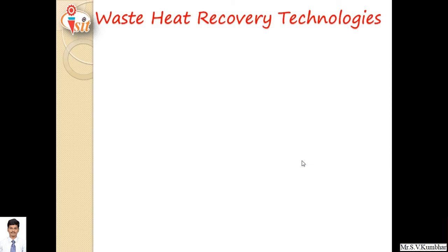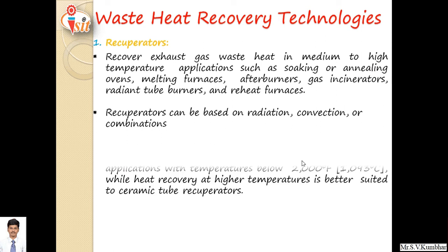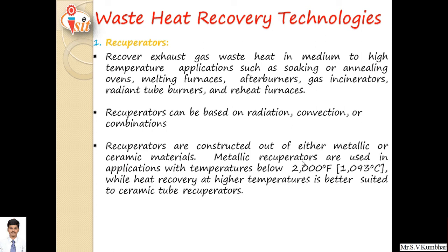Now, waste heat recovery technologies. The first one is a recuperator. Recuperators recover exhaust waste heat in medium to high temperature applications such as soaking or annealing, melting furnaces, afterburners, gas incinerators, radiant tube burners and reheat furnaces. Recuperators can be based on radiation, convection, or a combination of radiation and convection.